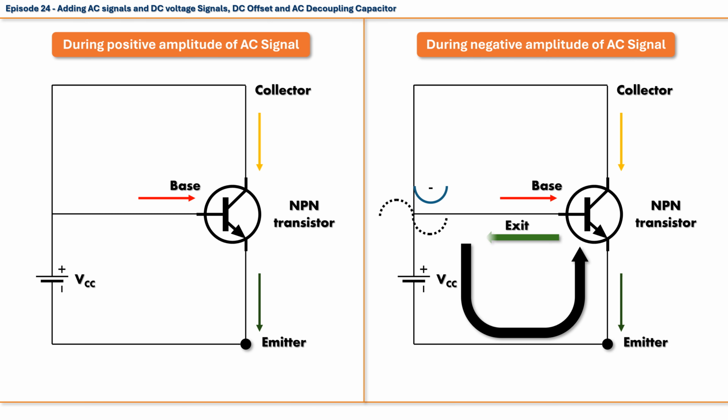What the heck? This is totally wrong, signals cannot enter into the emitter terminal, they do not get amplified in this way, and the base terminal cannot be the exiting point for an amplified signal, so this won't ever work.